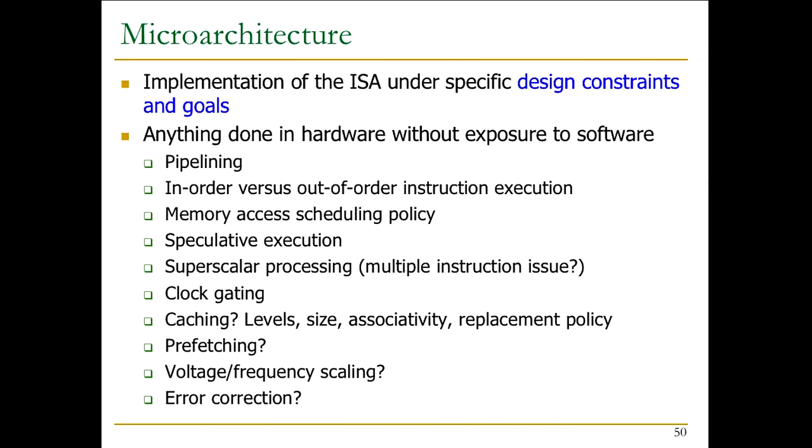Speculative execution, branch prediction, for example. You predict a branch, that's done internally, right? That branch prediction doesn't get exposed to the ISA, at least in most cases. We'll talk about branch prediction later on, but there are hints provided in branch instructions that are part of the ISA today. The programmer can specify this branch is likely to be taken. And that is part of the ISA. And that helps. If the programmer is correct, then the hardware can easily say, oh, this is likely to be taken. The programmer told me that, so let me jump to the target.